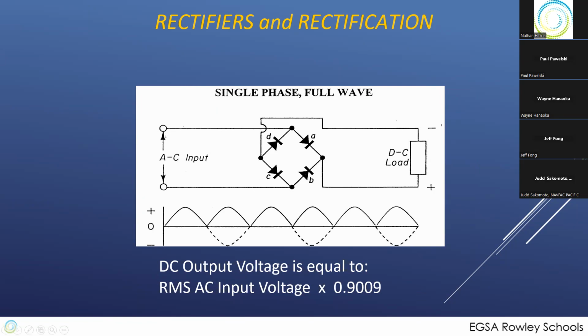Because let's look at how the power goes through. Let's say this is positive to begin with. Comes to this node. Well, at this node, it tries to go both ways, right? Well, it can't go that way. It's blocked, so it goes through this diode. Gets to this node. Can go both ways, but can't go through this diode, so it goes here. Positive side of the load. But then negative comes back, and it hits here. According to the diagram there, it should be able to go both ways. So why doesn't it go this way?